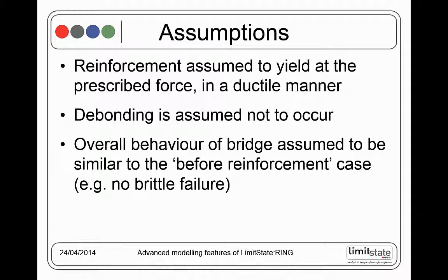We're assuming effectively that there's no debonding of the reinforcement, so it simply yields. That's the failure mode. And we also assume that the overall behavior of the bridge is similar to the before reinforcement case.